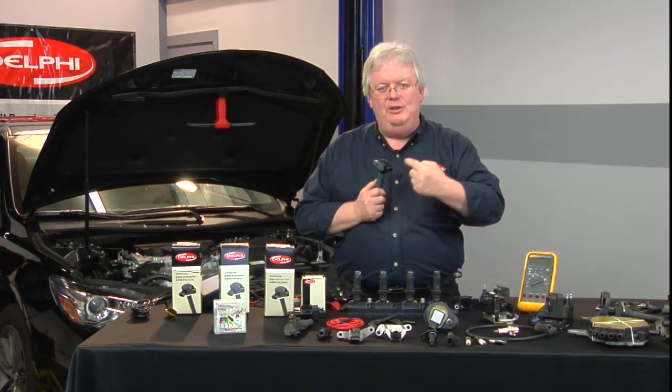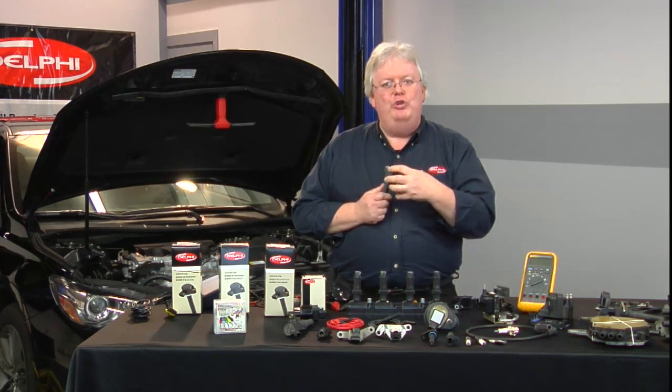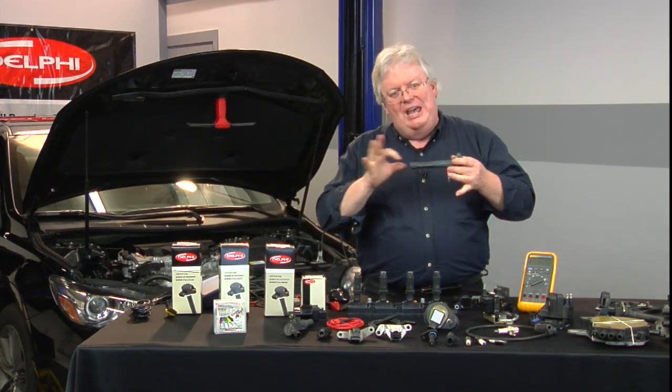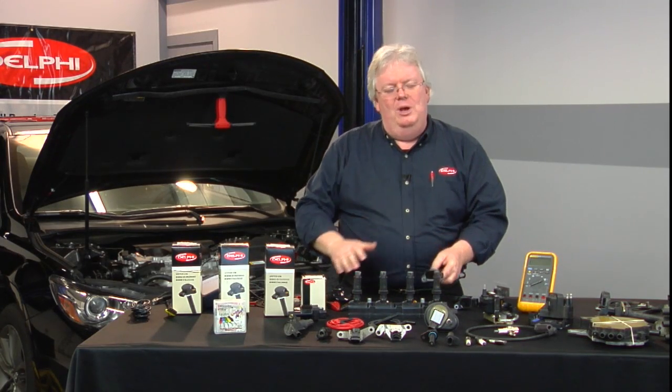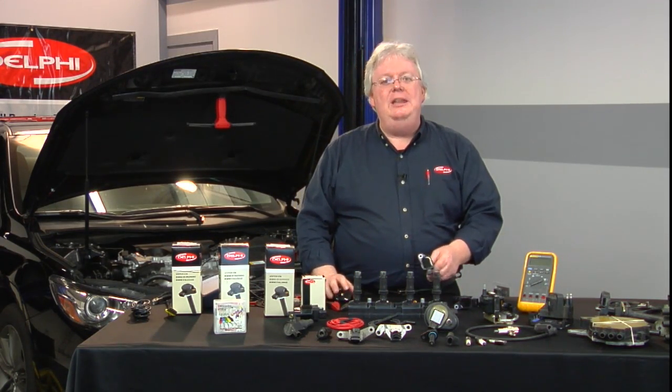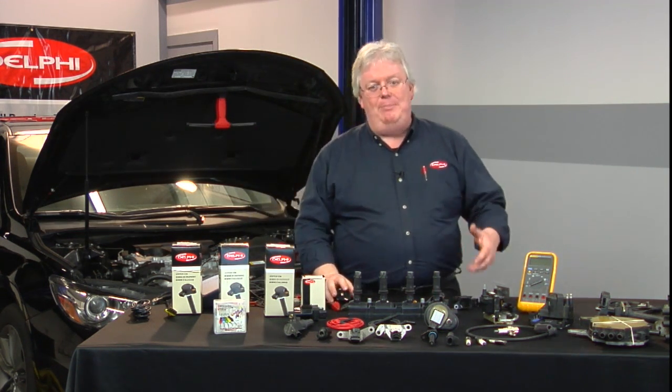We have its power and ground to power this thing up like any module, and that power is also there for the ignition coil primary circuit as well. So all this is working off of 3. Now we have a 4th wire added. Unless it's General Motors, that 4th wire typically will be a feedback circuit.